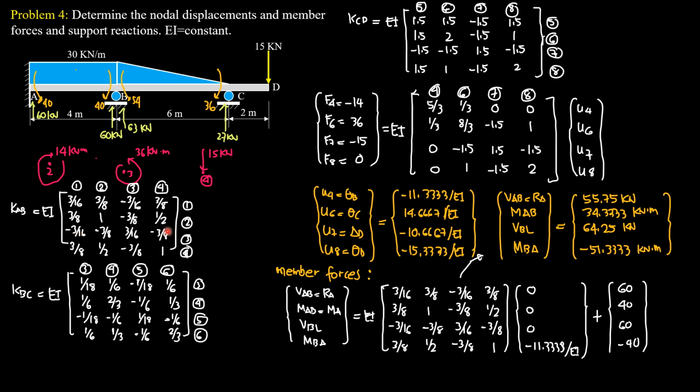Then the next row is the negative of the first row. For the last row, you copy the second row, except that we interchange the positions of 1 and 1/2. So 1/2, 1. So that's it. That's the technique. For those who are students in matrix structural analysis, you already know this. But for those who are beginners or not students in matrix, you have to study matrix first, the principle and the global stiffness matrix of an element.